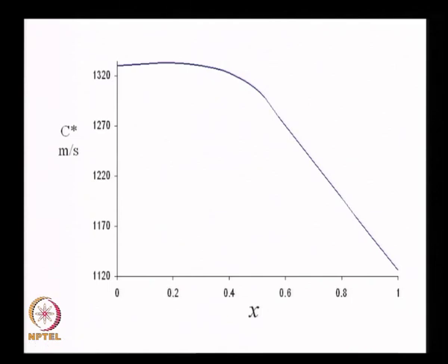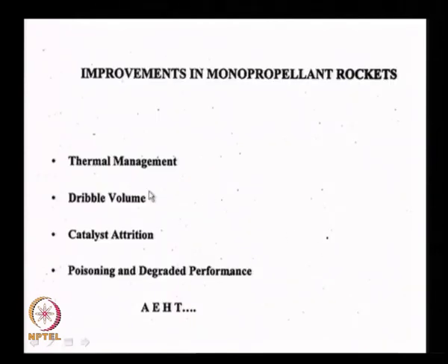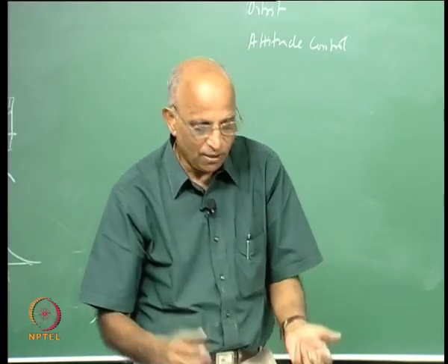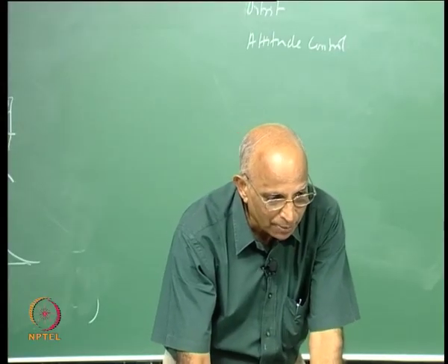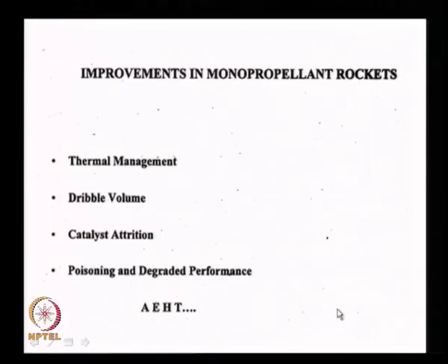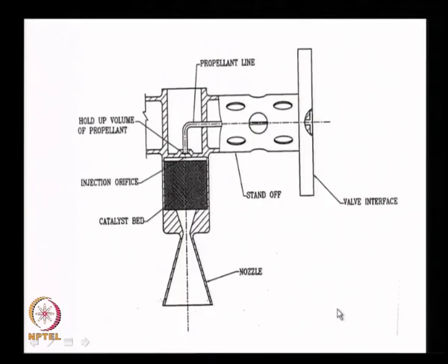Well, what are the problem areas in monopropellant thrusters? Well, the catalyst bed runs hot, therefore the injector runs hot, hydrazine could dissociate, and hydrazine being a monopropellant, it could as well explode, and therefore we must ensure we have thermal management. And how do we do the thermal management? We told ourselves, well, I have something like a fin which will dissipate the heat whenever the thing gets hot and remove the heat from here.